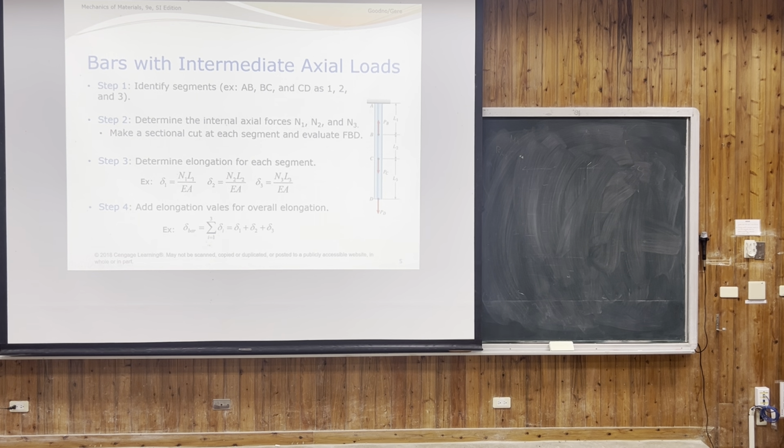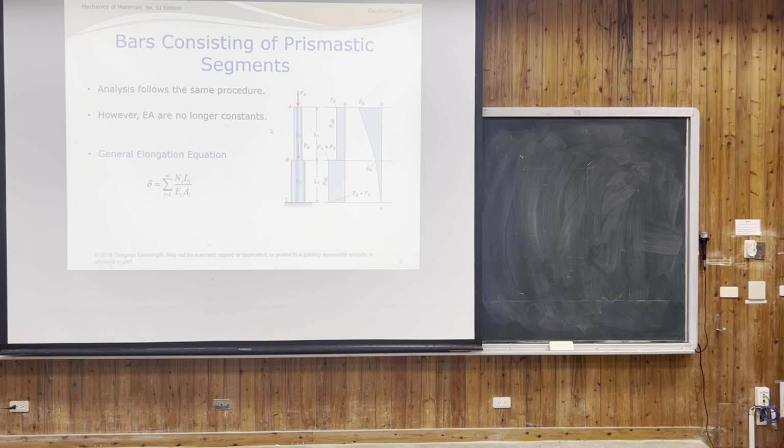When we hang rods with different materials together, in these kinds of questions you have to sum up the elongation of all of the segments, right? And this is another, same question but with different directions. The basic idea is to follow the general elongation equation, PL over EA, and we sum it up.